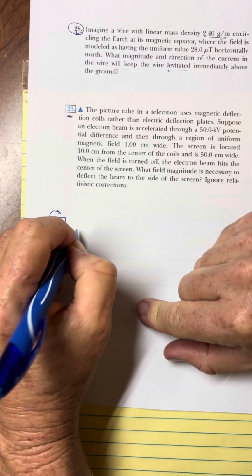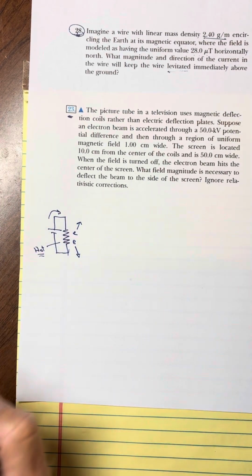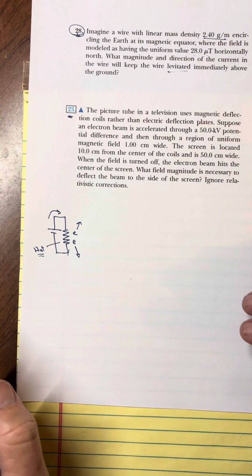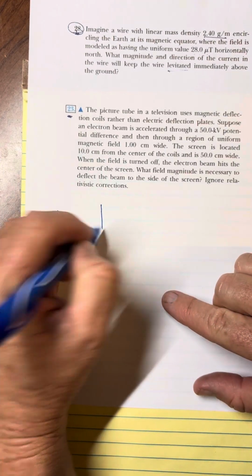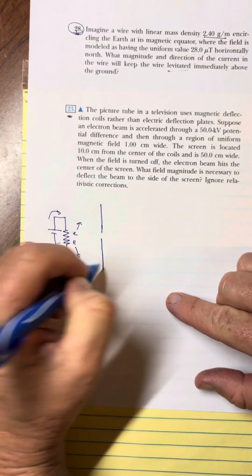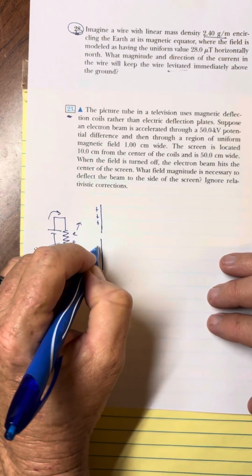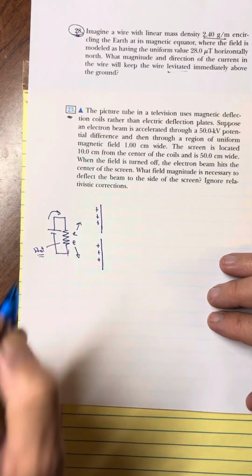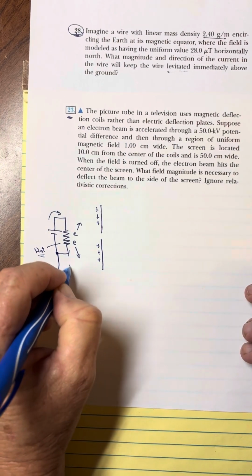In fact, it gets so hot, the tungstens bump into each other, and they boil off electrons, is the phrase we like to say, because they hit so hard. And then not far from them is another plate that we call the accelerating plate. And we make it positive in nature, and we usually do that by hooking up another battery.